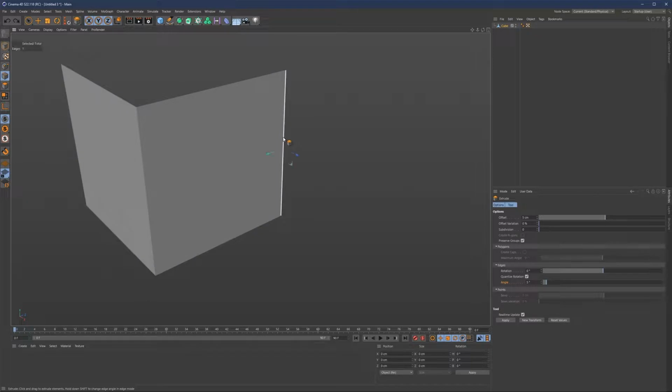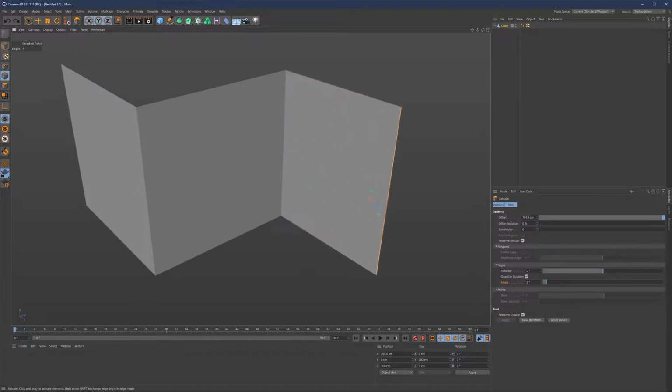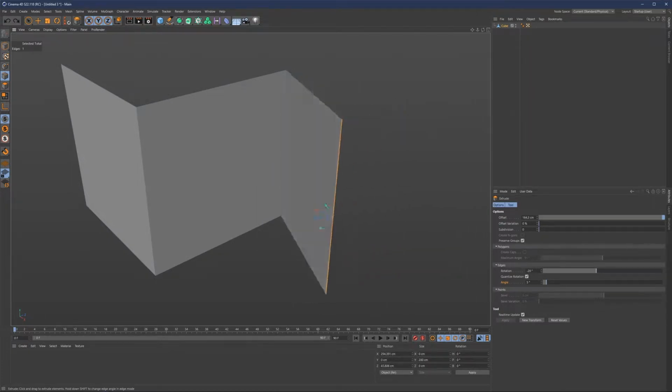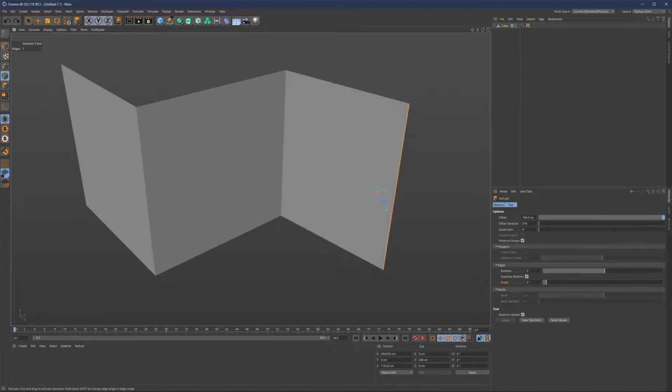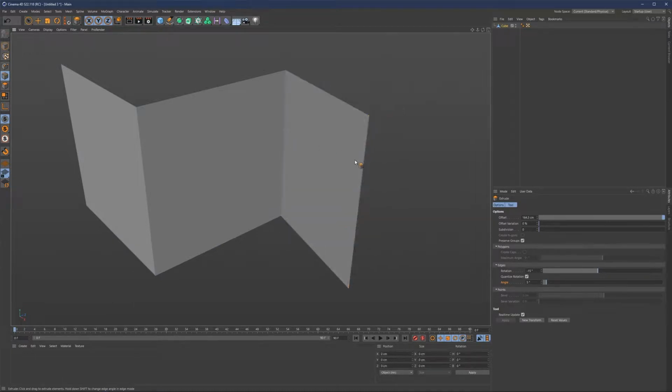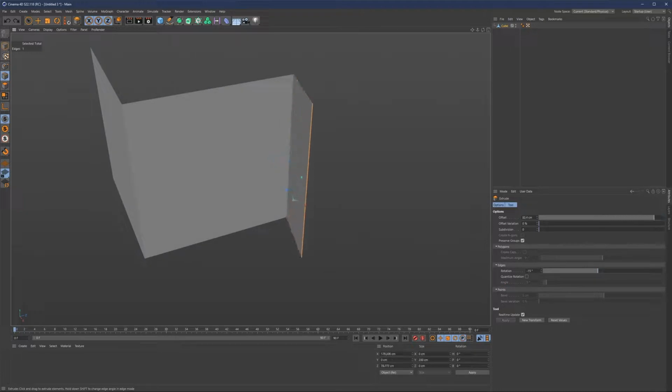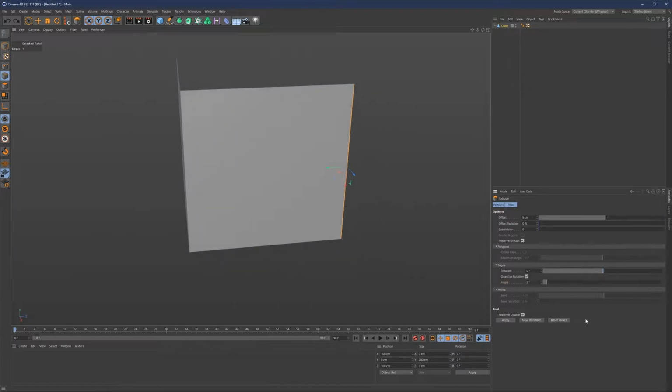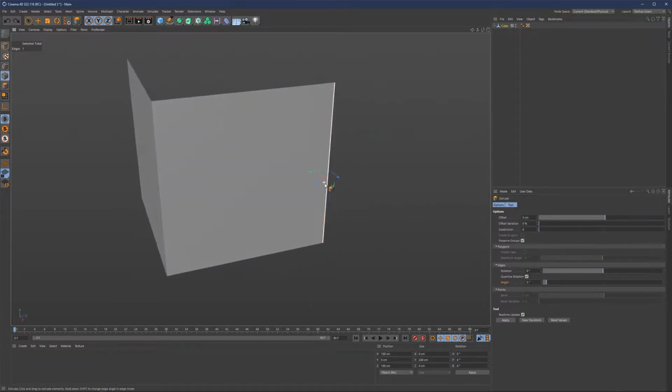This simply means if you now hold and extrude, you can hold the Shift key, and while you hold Shift, you will notice that it snaps to this sort of 5-degree angle, the one that it's already defined. If, for example, this would be off, and we now do another extrusion and I hold Shift, you will see that now it will move without any restriction. So it will not snap to any angle. All right, let me reset that again and let's see what else.